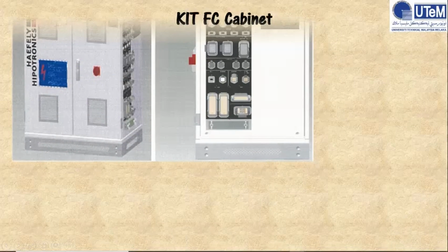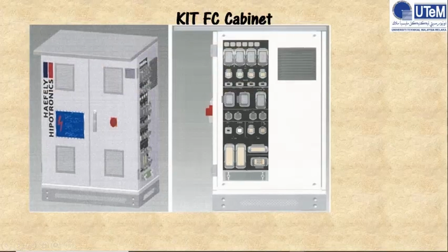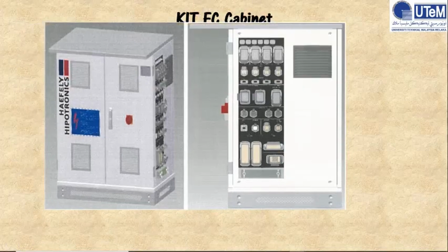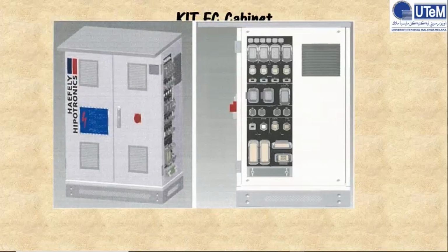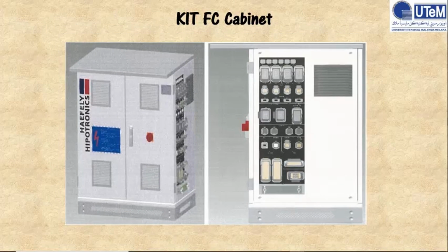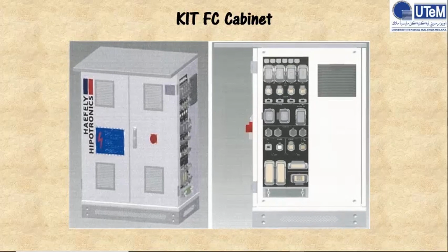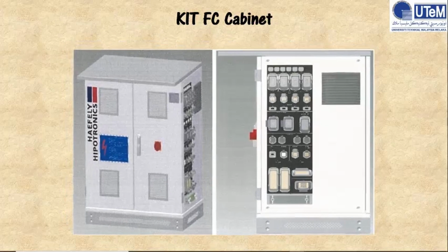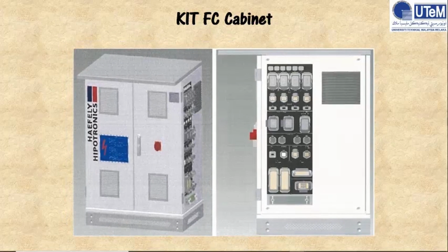Task 1 is about how to trace the power cable circuit. To trace the connection of the power cable, it starts with the power isolator and will be connected to the power cable. In the power cable, there are brown, black, grey, green and yellow, which is for earthing, and blue, which is for neutral, and it continues to connect with the power block terminal and will be terminated in it.